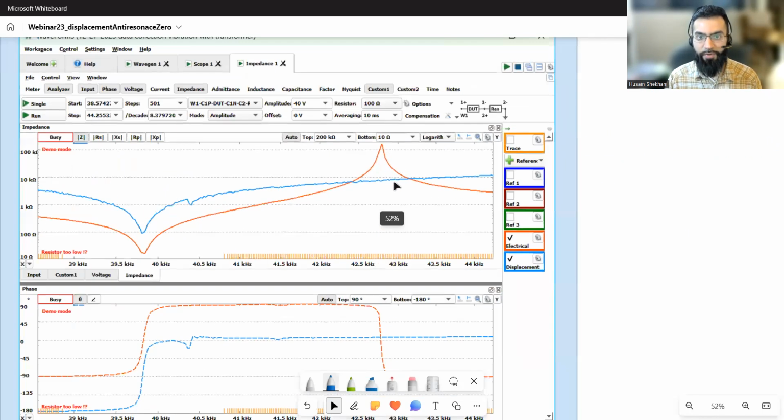That being said, the anti-resonance is very useful for power delivery, because it is a real resistive load. And it's nice that it's not at resonance, because the displacement is much more stable. If you put 500 volts at anti-resonance, in a loaded and unloaded state, it'll have approximately the same displacement. That's not true for resonance. If you put 20 volts at resonance without a load, you probably have to put 100 volts at resonance with a load.